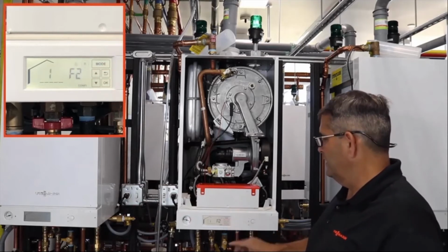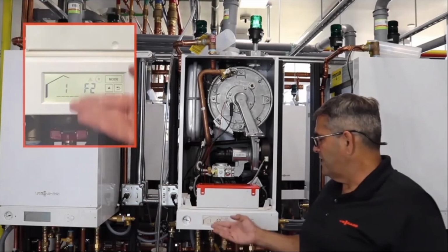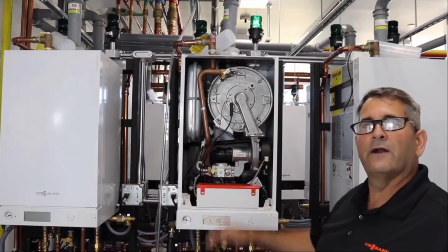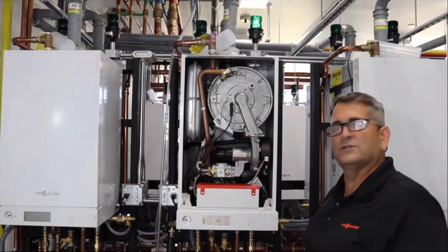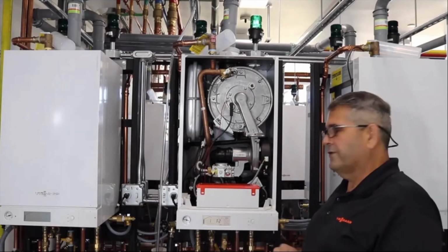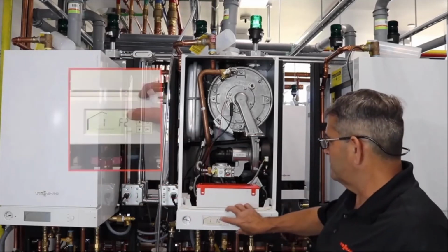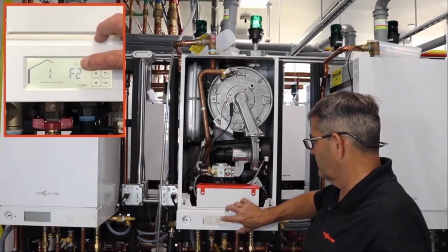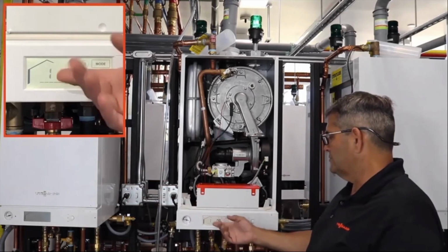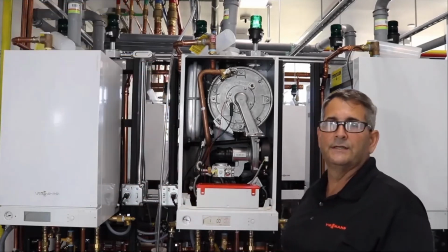Hit OK. And as you can see, it stores our last top 10 faults. We have 2 here, and we're going to clear all of those before we leave for the next person that's coming to the job, if he happens to know where to look for the fault codes, and you can take a look. They'll be all zeroed out. So we're going to press and hold the R button. They all turned to 0, so now we cleared all the faults in our fault history.